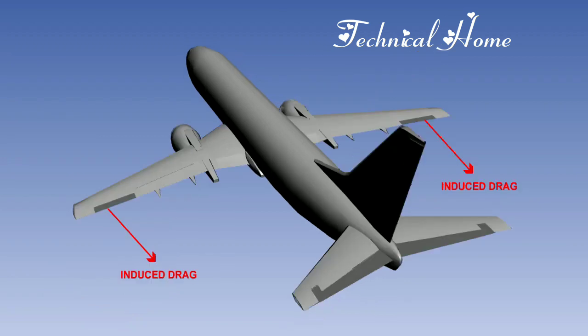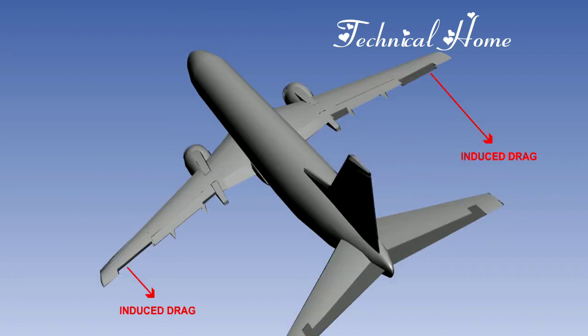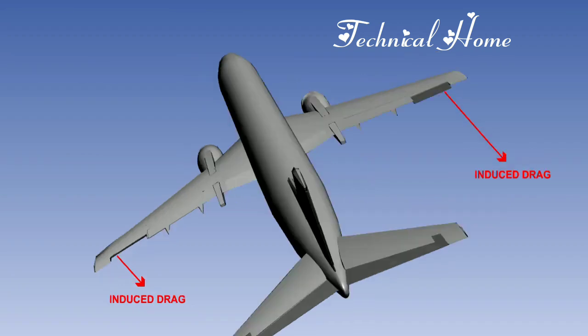An undesirable side effect of the use of ailerons is adverse aileron yaw. The increased lift on the upgoing wing gives an increase in the induced drag, whereas the reduced lift on the downgoing wing gives a decrease in induced drag. The difference in drag on the two wings produces a yawing moment, which is opposite to the rolling moment. That is, a roll to the left produces a yawing moment to the right, and a roll to the right produces a yaw to the left.